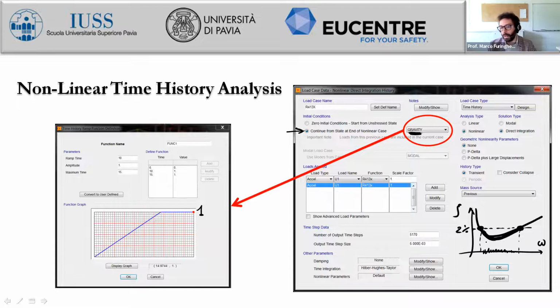Generally we don't account for additional damping just for a seismically isolated structure, because there is already the hysteretic damping provided by the devices. If we do have it, it is mandatory to consider additional damping. It should be limited to 2%, maximum 5%, and according to the Rayleigh formulation, with a very wide range of angular frequency.